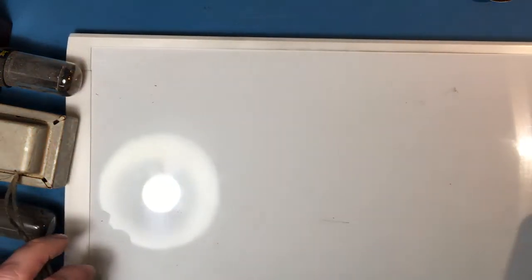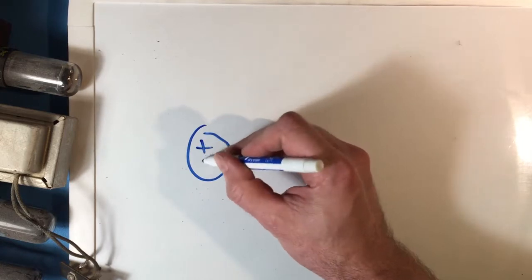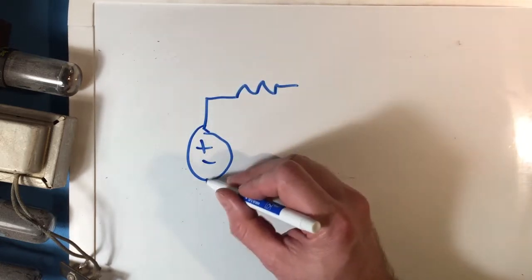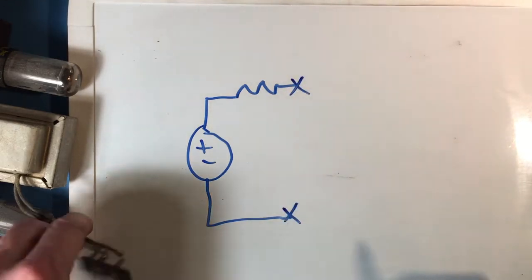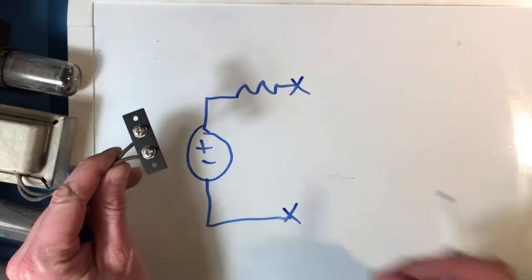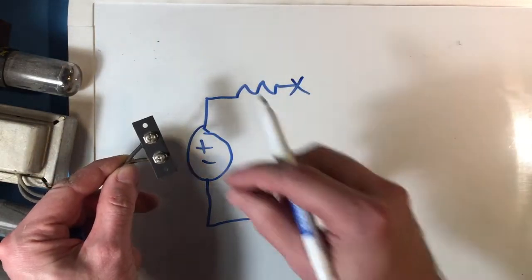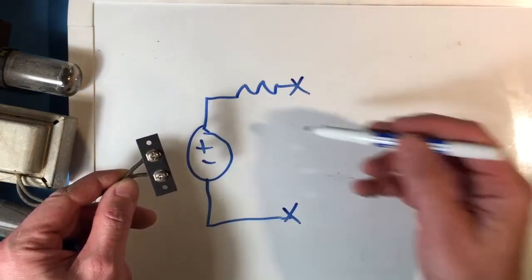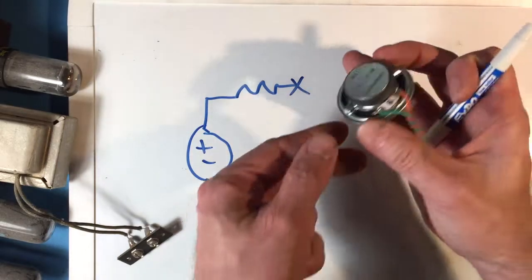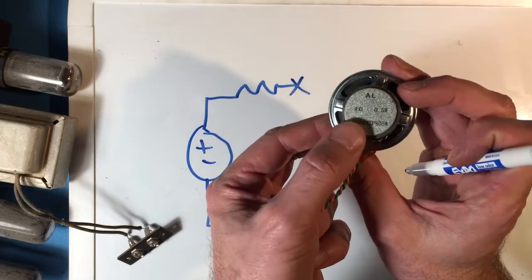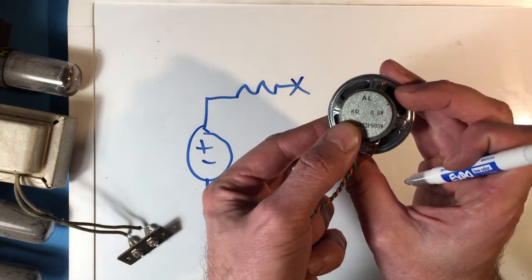And so you learned in lecture that, if you're lucky enough, you could model a circuit, even if it's very complex, if the circuit is linear enough, as a voltage source and a resistor right there. And these 2 terminals right here are the terminals on the audio amplifier. There's tricks that you could use to measure these parameters, these Thevenin parameters, to get a linear model of the amplifier. And the speaker claims to be an 8 ohm speaker, which is somewhat true. We'll take it on face value right now.